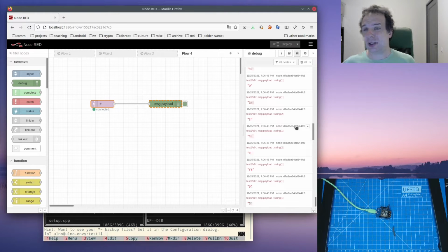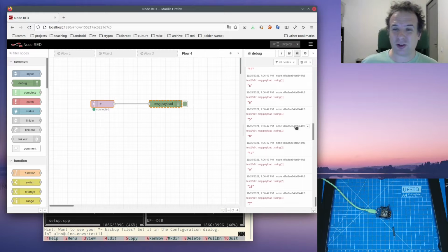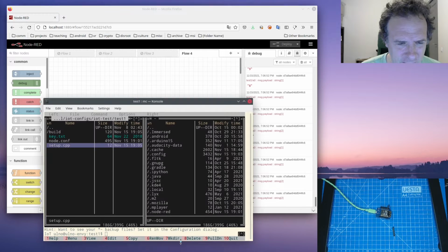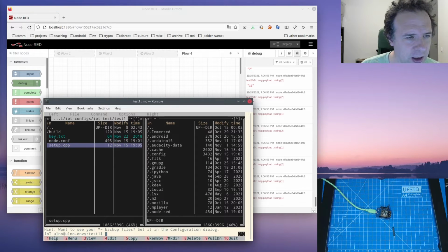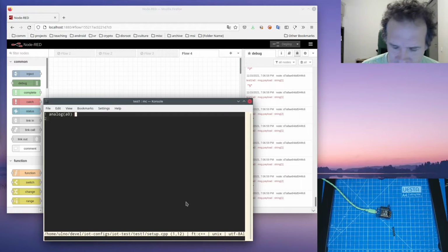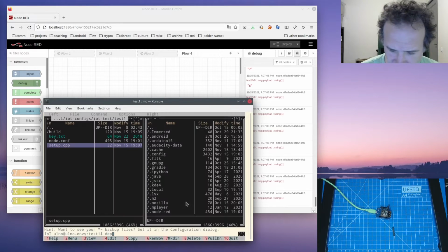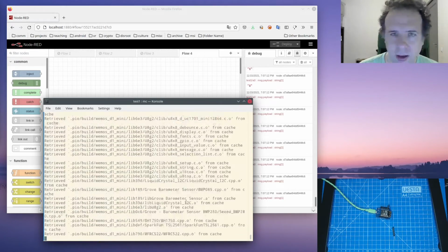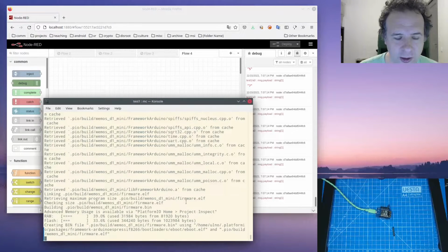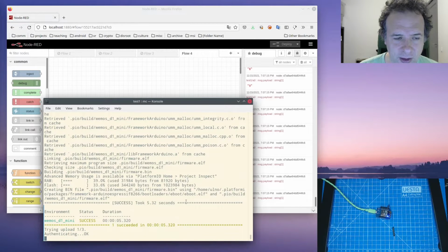So you can actually build a simple touch sensor with this, but it's kind of too many values, isn't it? So let's add a small filter. We added a filter average, and it just gives us something every 100 values only. So let's deploy that. And there we should get a little less, but averaged values.